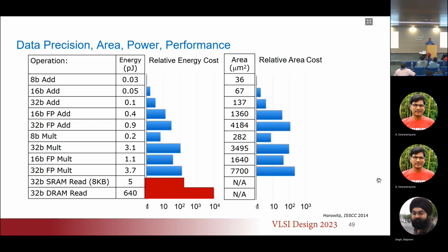So again, when I'm choosing my tile size, the tile size is coming from the cache or whatever memory that I'm going to use, and the chunk of the computation that I'm going to accelerate, that chunk size is going to be dictated by how many fetches I want to do. And so I want to do an integral number of fetches so that I'm not wasting any space in a fetch operation. Every fetch operation is completely full, completely packed. I don't want to run my bus 75% full, right? I want every seat occupied in the bus.